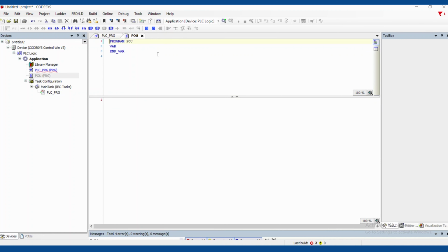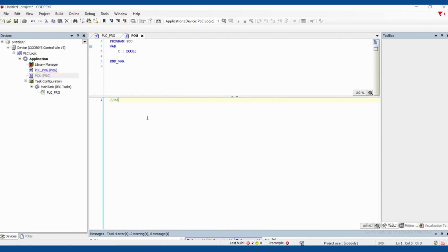Let's have a look at structured text. If you are already familiar with structured text, this is going to be a piece of cake because it's all using the keyboard. We can make new variables, something like this. They can also have comments, although they won't show up down here. But we can put comments in structured text kind of wherever we want. We don't have to turn on the irritating take up space feature.